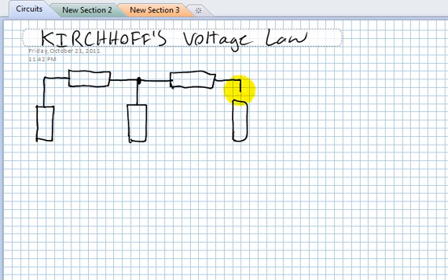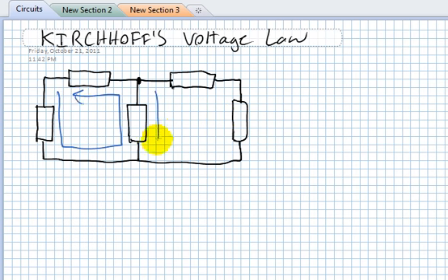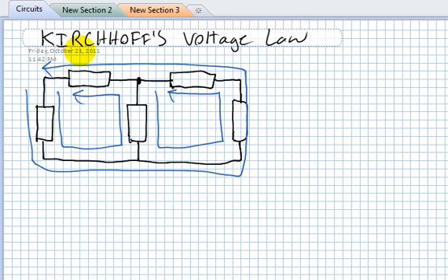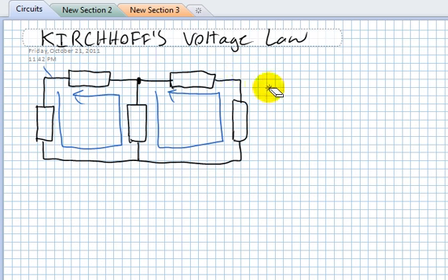You have these 5 circuit elements, and we have to write these mesh equations for them. Now you have to look at how many meshes we have, or how many loops. I can tell you right now we have this loop, this loop, and this loop. You don't really use the master loop outside. You can use any loop inside of a circuit when using Kirchhoff's loop laws.